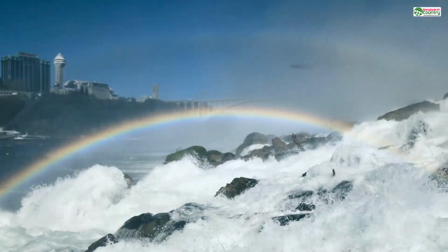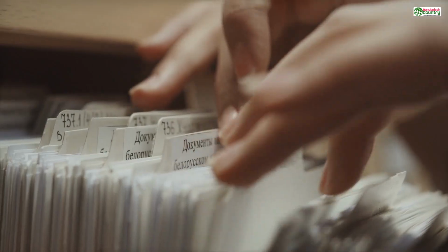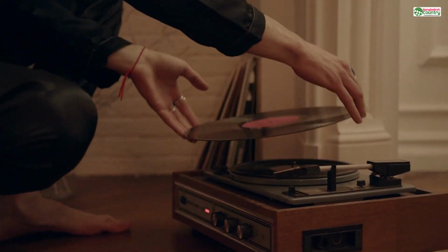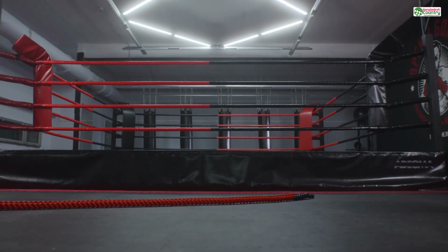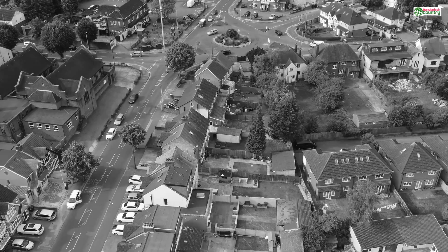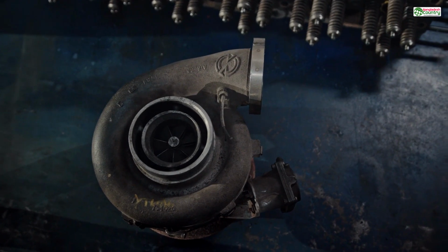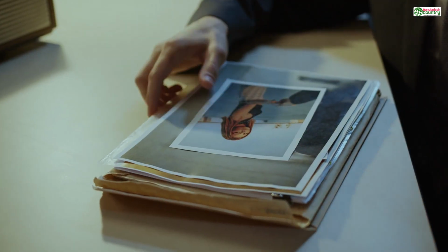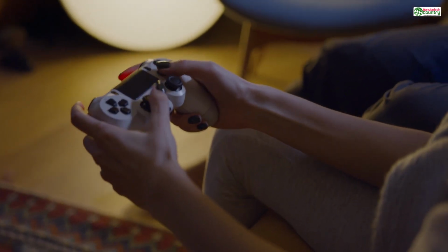When you're dealing with infill, you're essentially balancing a classic engineering triangle: strength, speed, and cost. More infill means more strength, but it also means a longer print time and higher material cost. Less infill is faster and cheaper, but your part might snap under pressure. Your job is to find the sweet spot for your specific project. This control comes down to two key settings: infill percentage and infill pattern. Let's break them down. First, infill percentage.